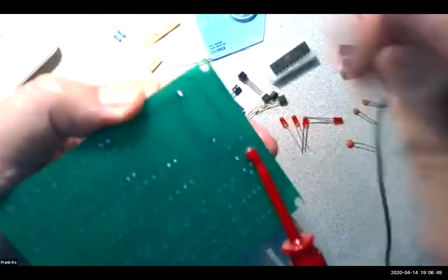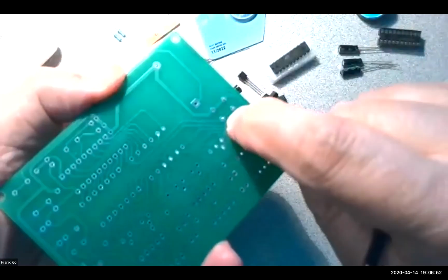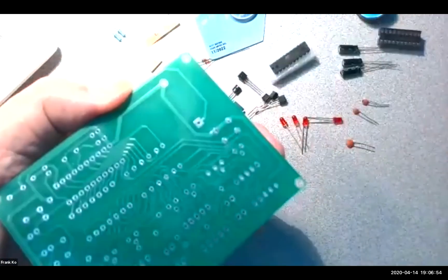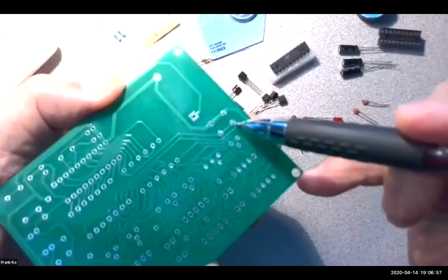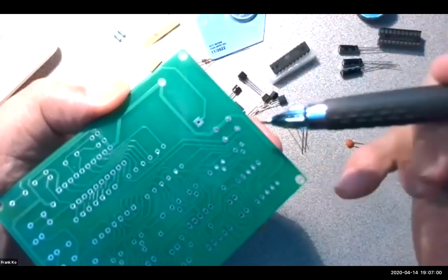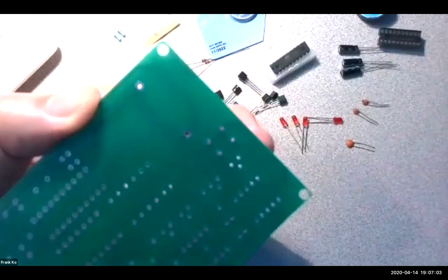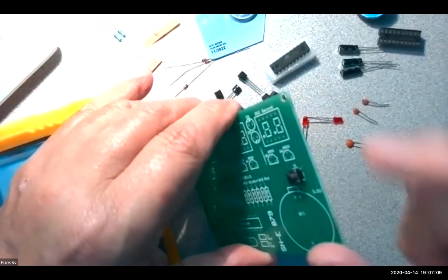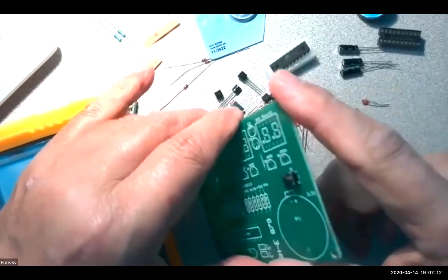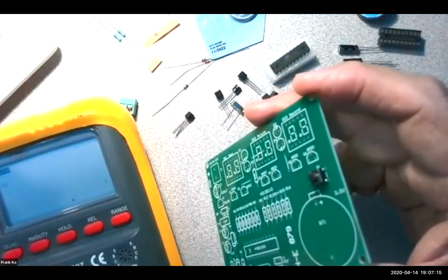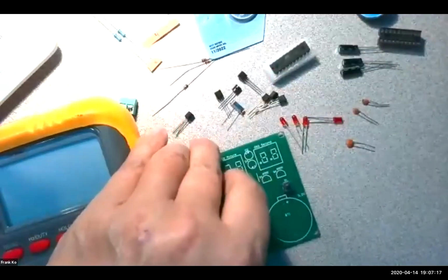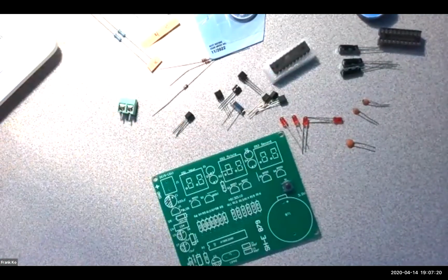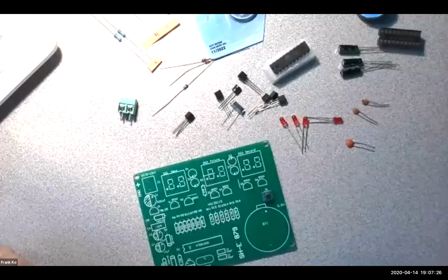It will give me continuity between the thin trace and the large trace on the board. It'll give me continuity between these two pins down to these two pins as long as your orientation is correct. So any questions about how that switch is supposed to go on the board? That would be the only tricky thing: if you push that in 90 degrees rotated, this thing will not work properly. This guy there, this guy here, okay, and this guy here. Cool. All right. Any overall questions concerning the project kit?